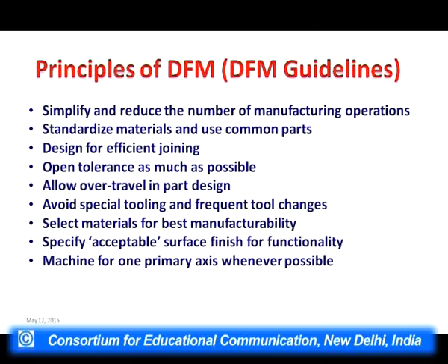Manufacturing operations should be limited, as small as possible, and standardize materials and use common parts available in the market. Most of the products and their assemblies should use common parts. Design for efficient joining. Finally, we have to join the different parts. There should be efficient methods and procedures for joining also.